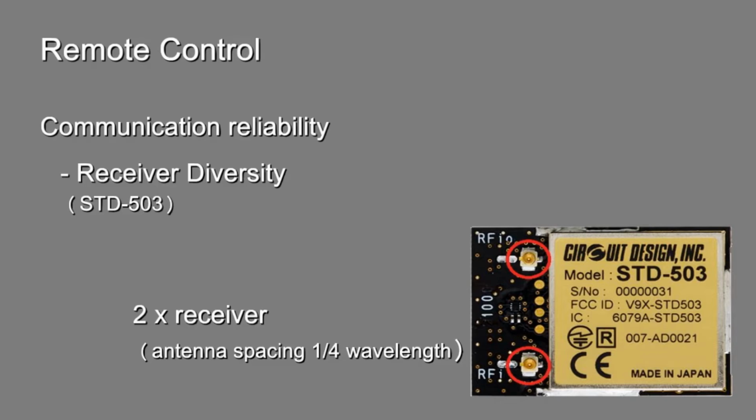The ST503 module incorporates direct sequence spread spectrum provided by a custom ASIC. By spreading the signal with a chip code, this allows reliable communication in the 2.4 GHz band with minimal interference from other 2.4 GHz devices. When operating in the field, high blocking performance of our modules allows reliable communication in the presence of other on-site equipment transmitting in adjacent frequency bands. Narrowband and channel selectivity allows channelized operation, meaning multiple systems in one area.